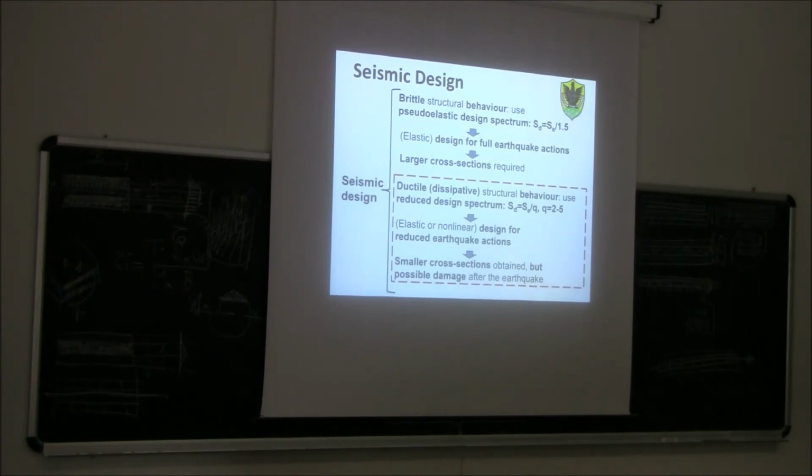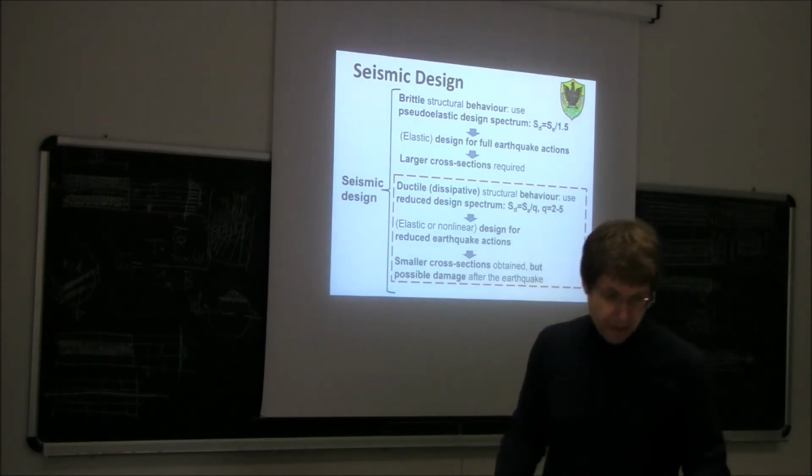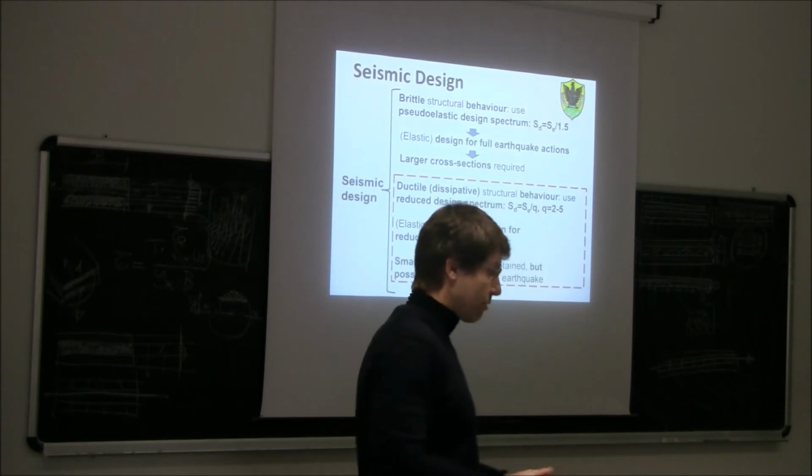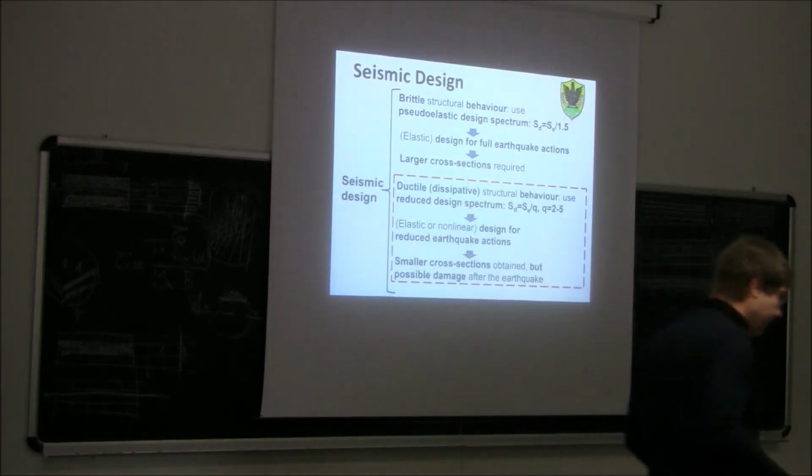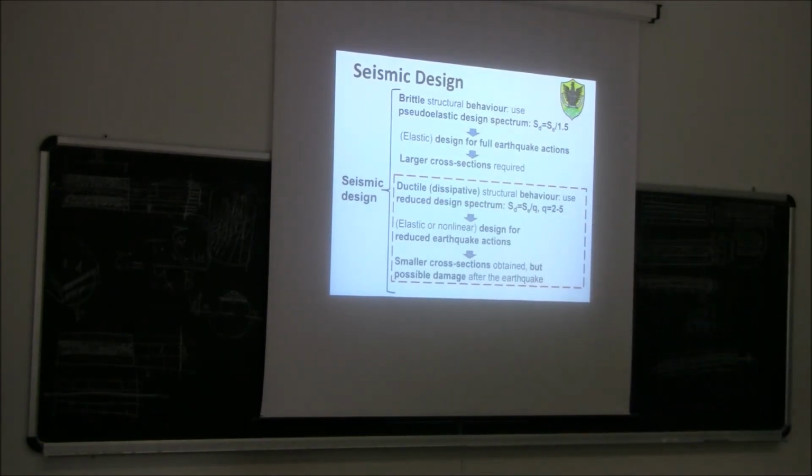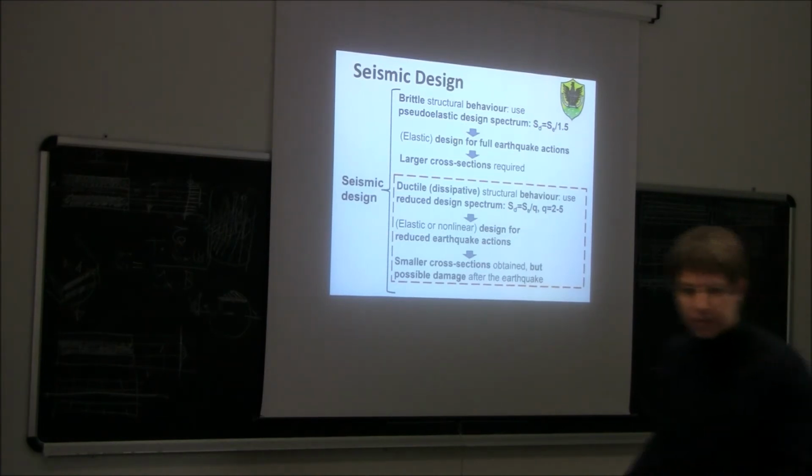If you remember, for reinforced concrete, all your ductility was coming from the concrete or from the steel? From the steel. So concrete was actually a brittle material, the steel was the ductile material, and we would have to take into consideration some possibilities. For example, we had to prevent shear failure, because shear failure is always brittle failure, using capacity-based design. So we have to see now how to adapt all this design philosophy to the case of timber.